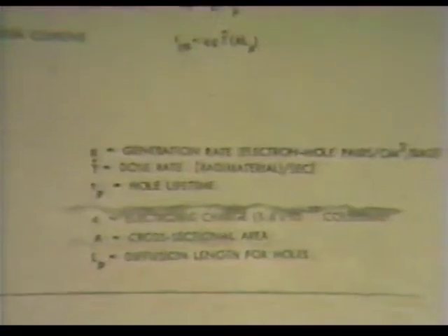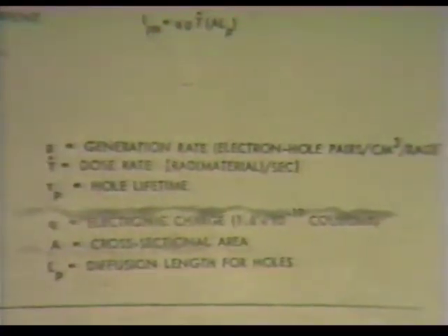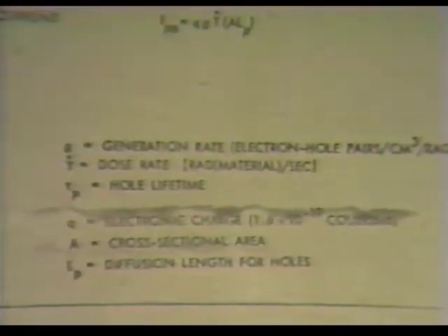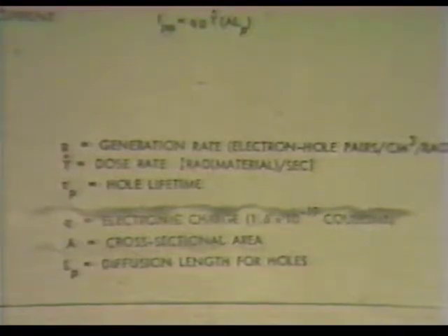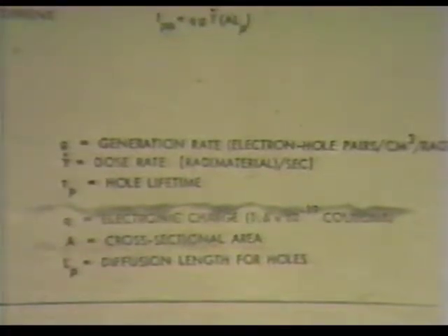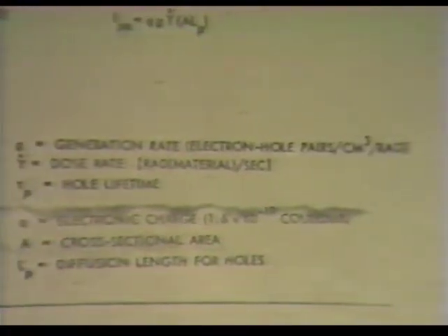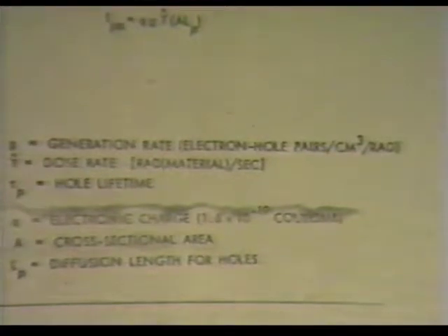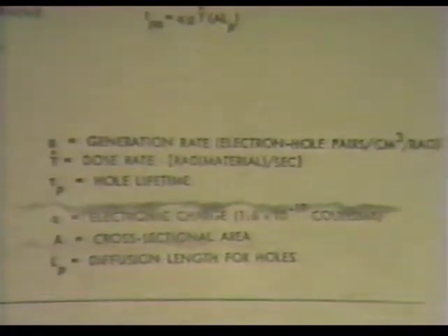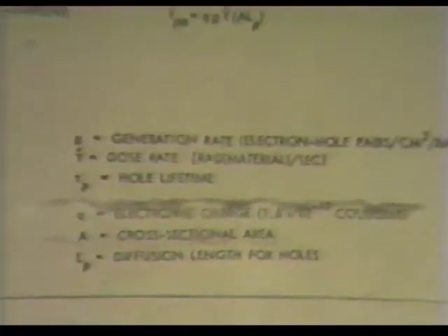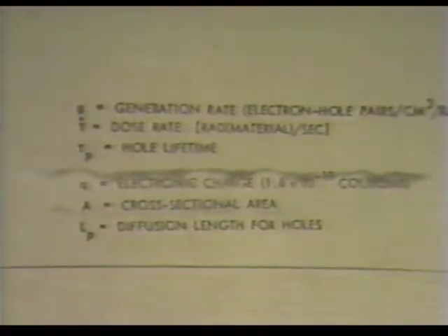And if you've got it sitting in one of John's logic circuits trying to perform a function, when it's supposed to be off, radiation turns it on, it's going to mess up your logic. So high dose rates just totally wipe out your logic states. It's what we call dose rate upset, and it happens. And it happens to any type of active device that you can put in an ionizing radiation.